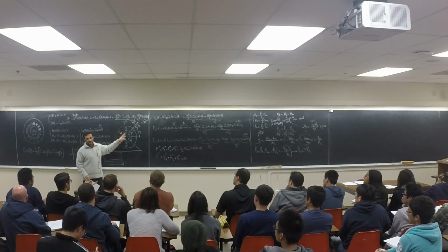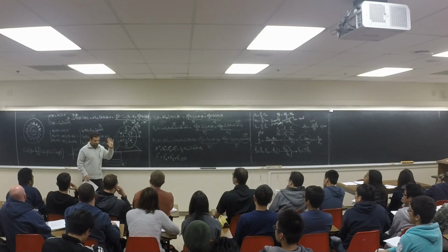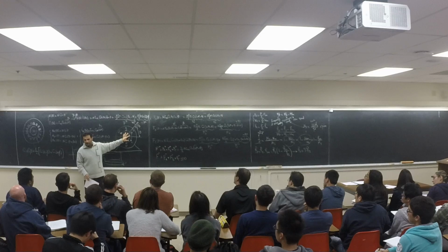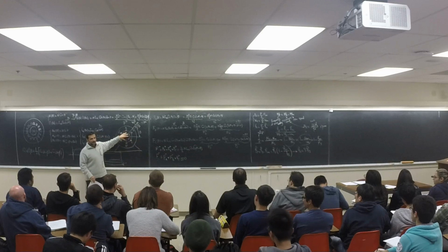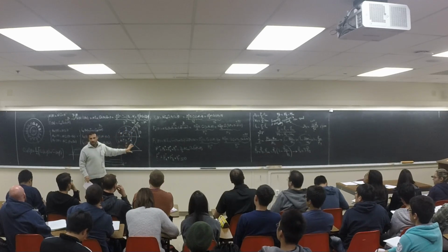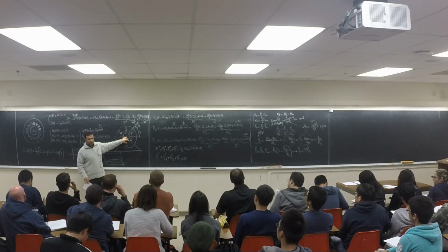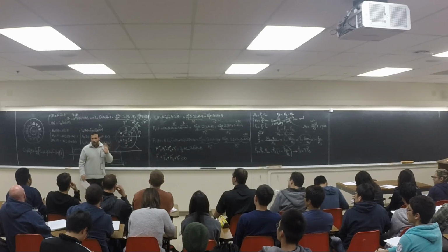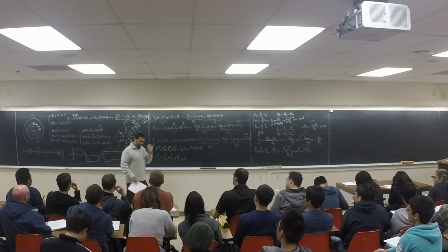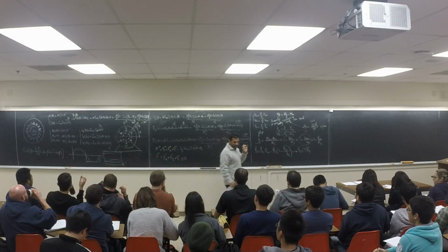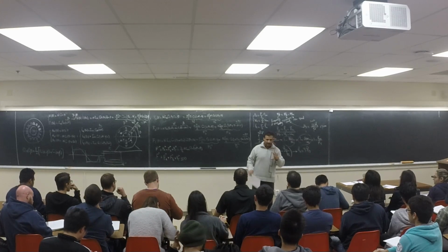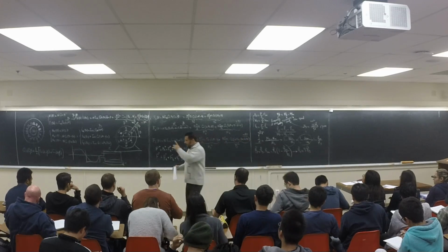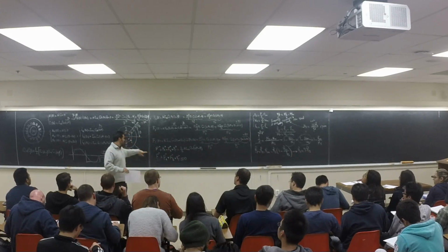I'll give you an example. I say this is 60. How much frequency is there here? It's 0.6, right? It's almost zero. It's not perfectly zero, but for example, 98% of the loss is in the stator. With 2% slip, in this case, 99% of the loss is going to be in the stator, and 1% is going to be in the rotor. Because the rotor is almost DC. 0.6 hertz is not perfectly DC, but it's almost DC, right? So opposite to the DC machine, where we said the magnetic loss is in the rotor and the stator is loss free, here the magnetic loss or core loss is going to be in the stator.